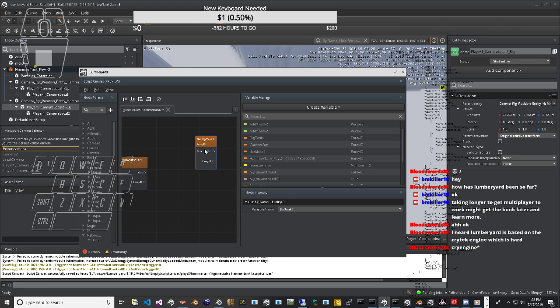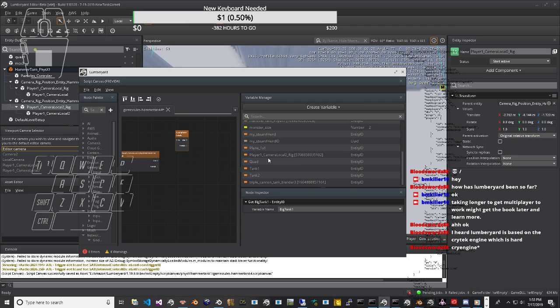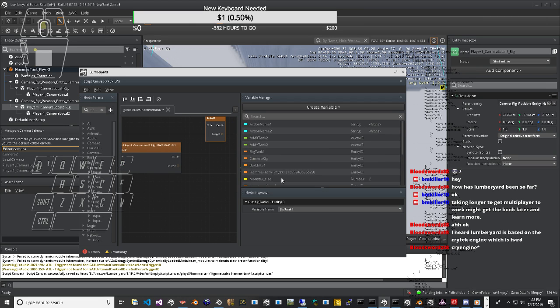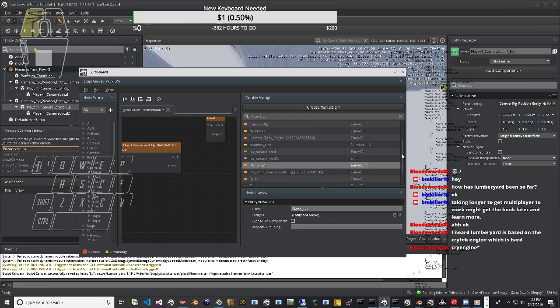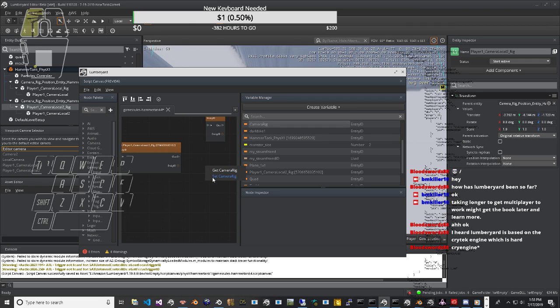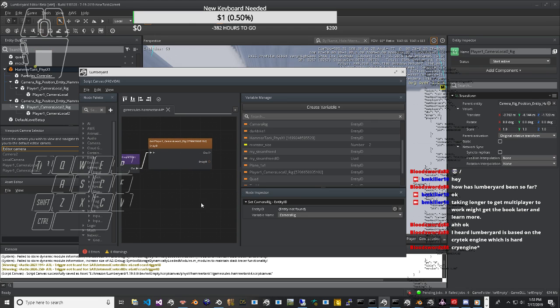Path ceases to exist when the car stops moving. Path heading is the angle of the projection of the velocity vector on Earth's xy plane with respect to the x-axis of Earth. Milliken calls this course angle, Greek upsilon. Path heading, just like heading, is measured in the Earth frame. The side slip angle of the entire vehicle is the path heading minus the car heading. This is positive when the right side of the car slips in the direction of travel.